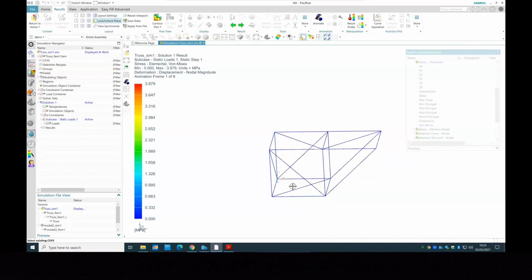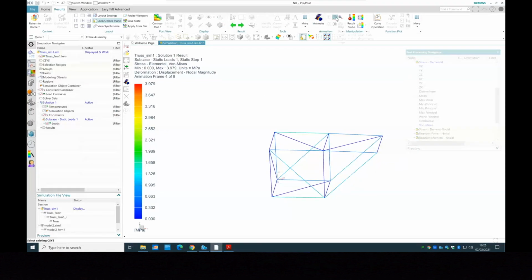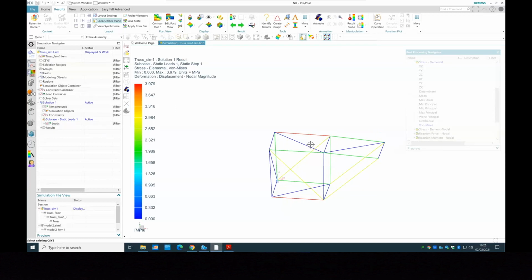So whenever you see the kind of red areas, these are the areas I have to go back and redesign. You will see then what's the maximum stress I will get on that. So we'll say these are the maximum areas. So I have to make sure that area will pass my expectation on that. So you will check the maximum force on there by the megapascal.